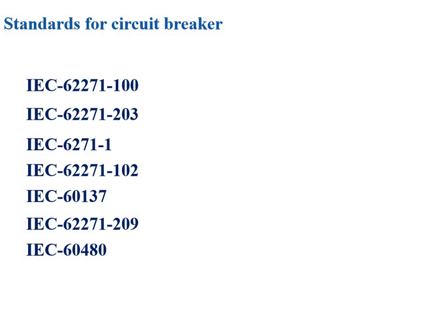The next is IEC 60480. This standard is used to check the sulfur hexafluoride taken from electrical equipment. Then IEC 376. This standard gives the specification and acceptance of new supply of sulfur hexafluoride. So for SF6 circuit breakers, both of these standards are required.